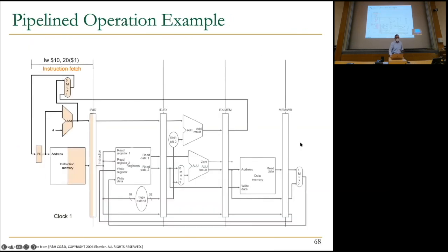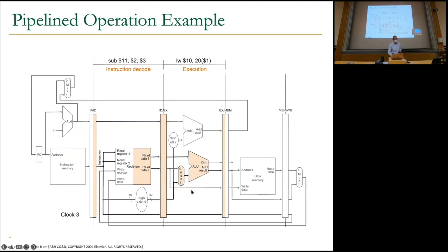Okay, so basically, what is this? In a pipeline operation, this load word has a destination register ID over here, and it has a bit saying that I'm going to write to the register. That goes to another logic over here. And this instruction over here has source register IDs, and it says I'm going to read source registers. And basically you have comparators. Comparators check whether the destination register ID over here is equal to any of the source register IDs, and whether the instruction here is writing, and whether the instruction is reading from the registers.